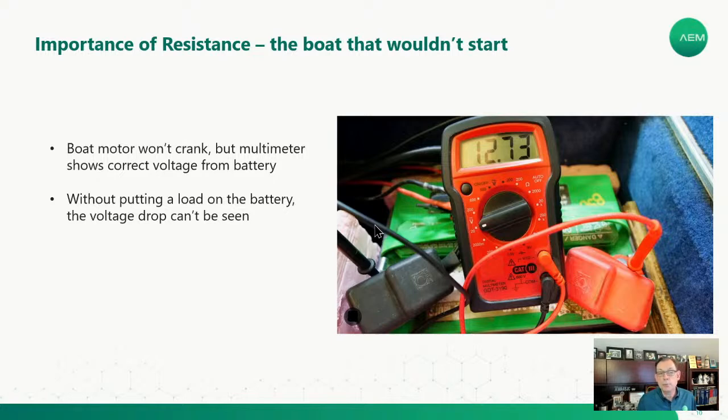And this is the difference when we talk about allocated power that we're going to show you in the PoE diagram here in a moment versus real power. So allocated power is the theoretical maximum, using that resistance calculation for a good circuit, that we should get 71.3 watts on a good circuit that has cabling in good order, and where we've got 90 watts at the source.